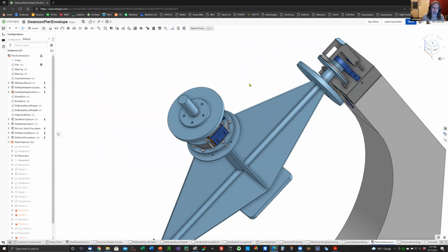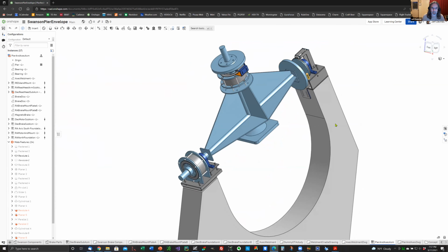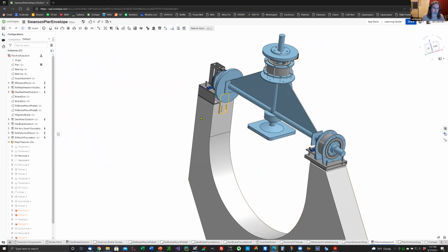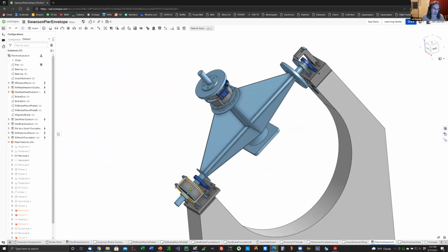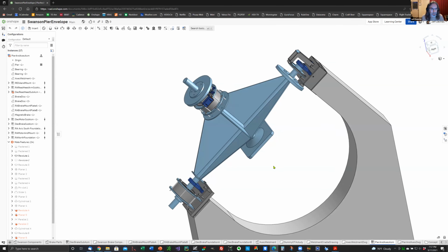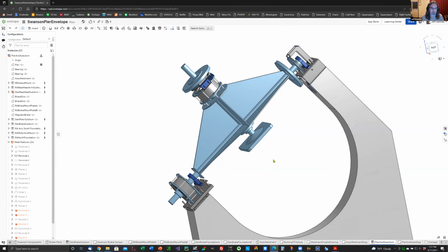The main thing that we're doing is replacing, you may remember we had a big wheel that had a wire drive over here, and there was gearing and motors over here. All of the gearing is going away. We're adopting direct drive motors, and that's what these two components are. These are large direct drive motors, so there are no gears, there's no backlash possible. They're extremely high torque motors and able to hold position quite well.